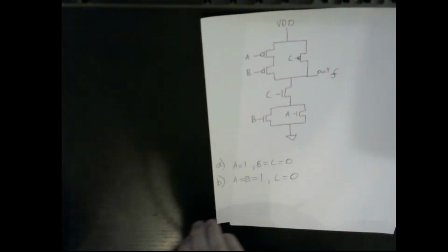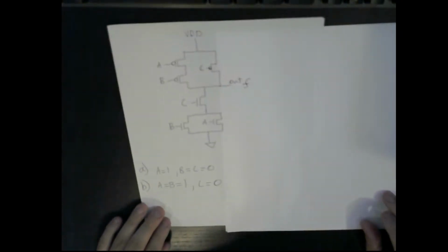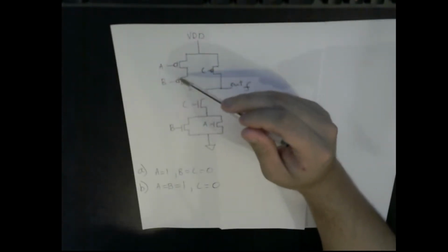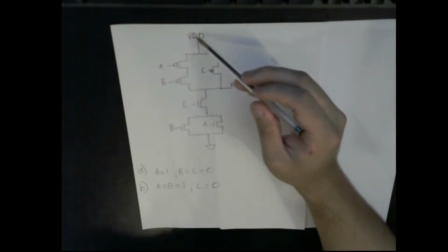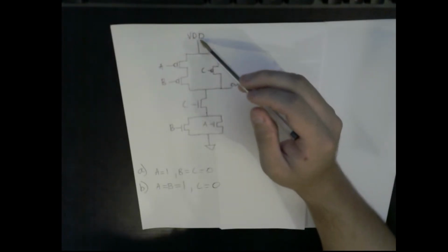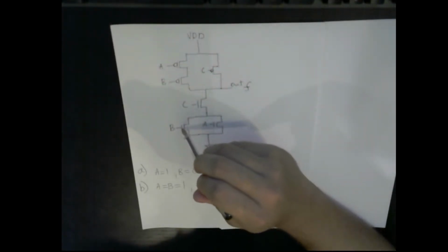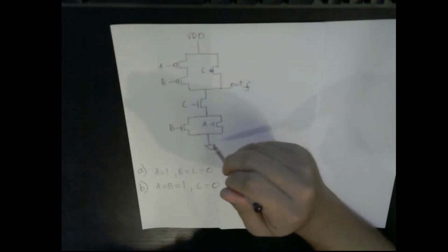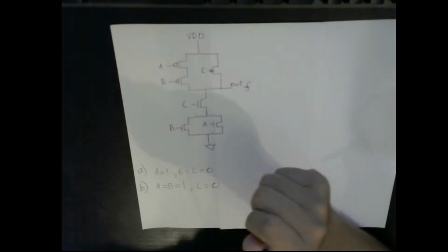So pull out this diagram here. I have an example of some CMOS gates here. We have our PMOS up top because they're better able to conduct VDD. We have our NMOS at the bottom because NMOS are better at conducting 0, right here next to ground.